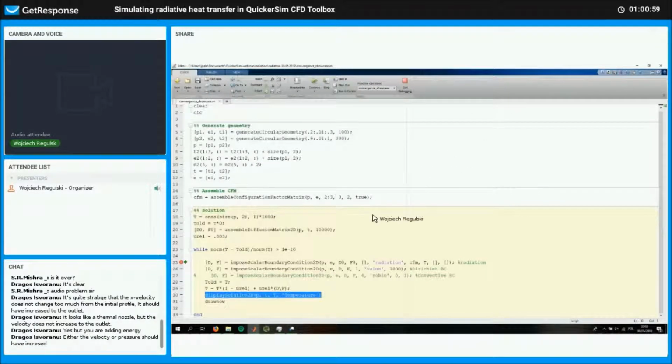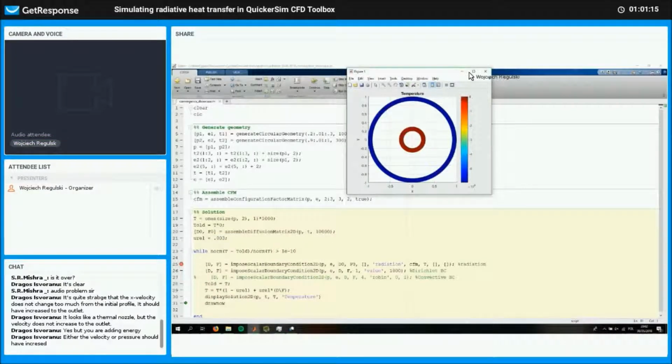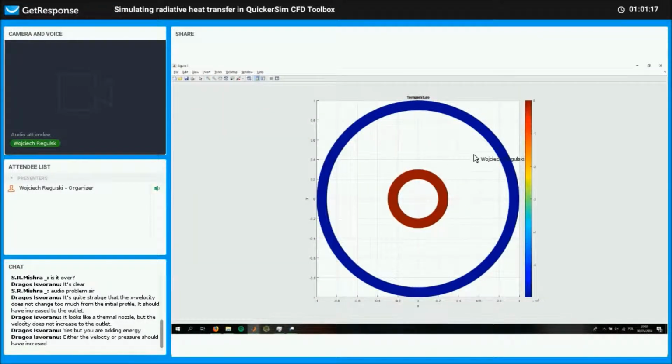What happens when we run one iteration, even with a very small under relaxation factor of like 0.003? Even with this, you can already see, because there's an unbalanced heat flux, we instantly get a ridiculous temperature, and it's a negative temperature too.